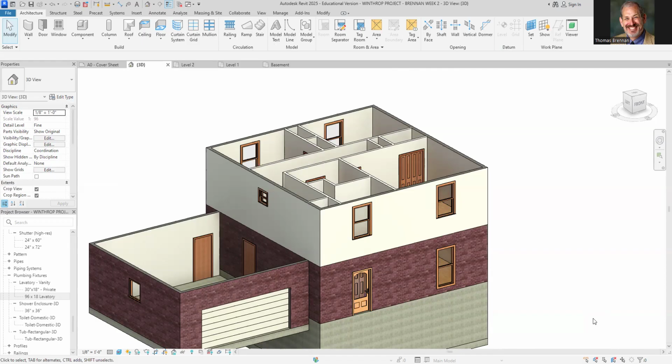And the other doors, I didn't give you measurements. The default offset from a wall is 6 inches, but I would take anything as long as it looks right. That's from the one after. 6 inches is the default though, so I didn't really put measurements on those. And when you take a look at it in 3D, it's going to look like this.